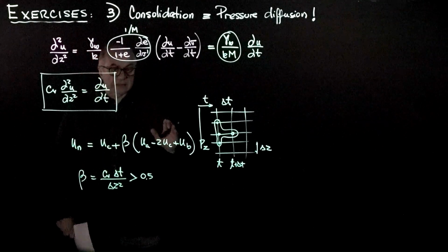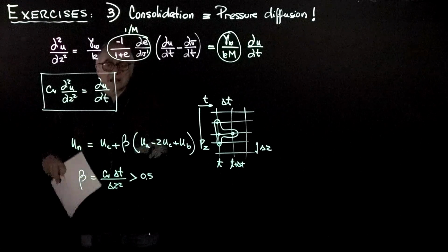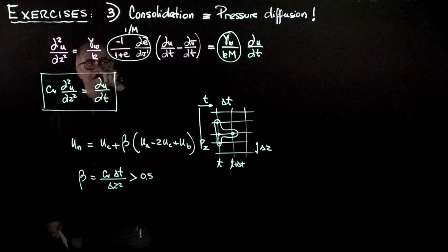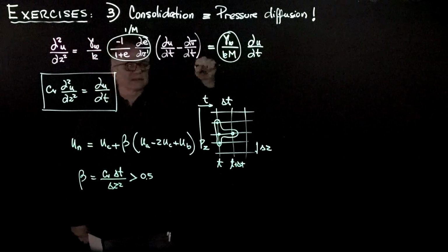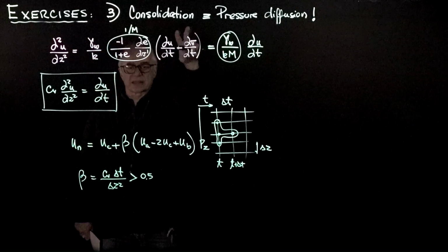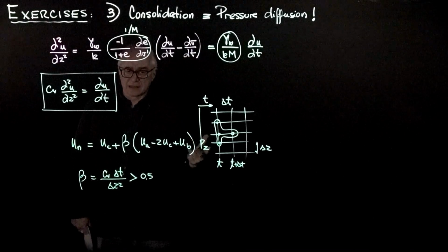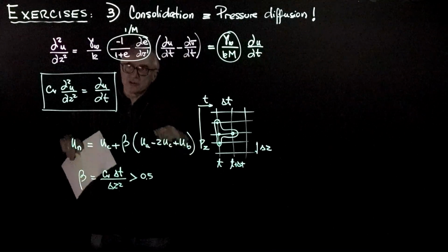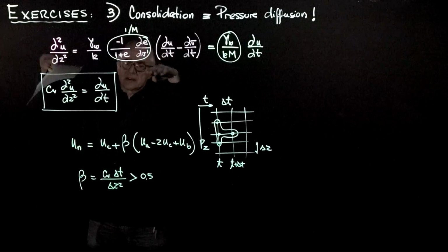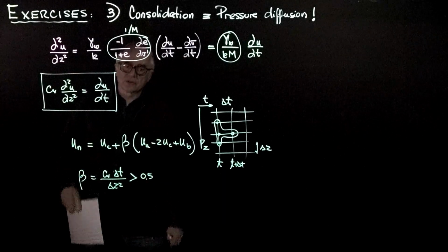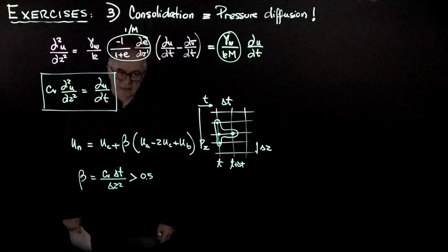Please, I insist that to get to this point, we have made a large number of assumptions. In this case alone, that K is constant, that the constraint modulus is constant, and that the applied stress remains constant. This may not be the case in your problem, so you have to go up in the stack of the derivation and remove some of those assumptions to be able to capture the problem that you have at hand.